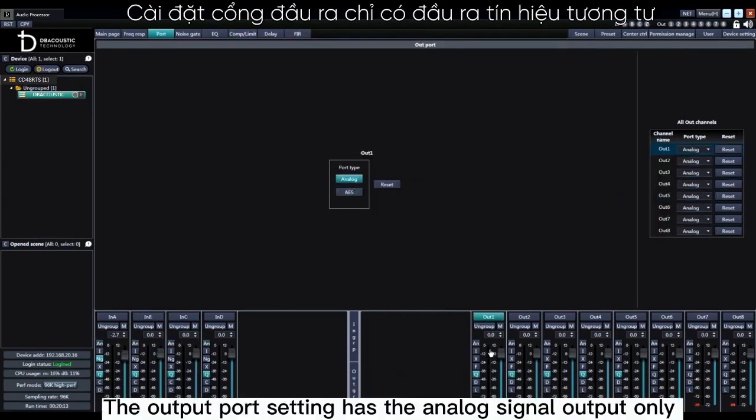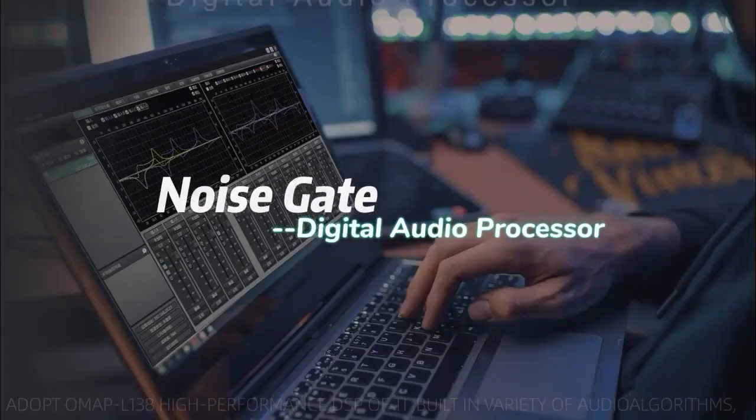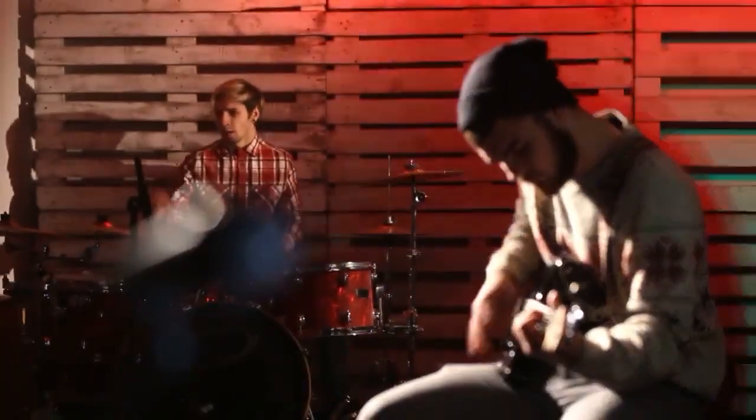The output port setting has the analog signal output only. AES output is a customized function. Only specific models have this function. Noise gate. This is noise gate setting. The noise gate compresses the small input signal below the threshold in proportion, which can effectively eliminate or reduce the environmental noise collected by the microphone and the noise introduced by the line.